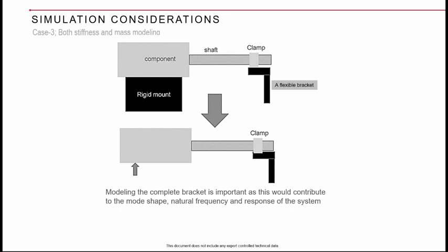Is it really required? For example, with a rigid mount here, I need not consider the complete engine for my meshing, right? I can avoid the complete meshing of the flange and everything here because they are quite stiff compared to the overall mount. Whereas here it is flexible.